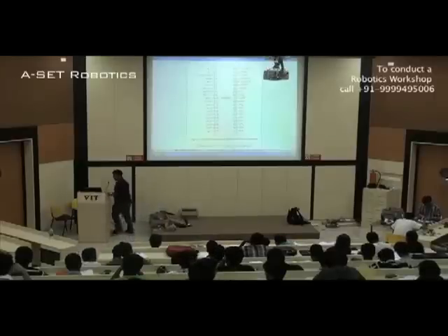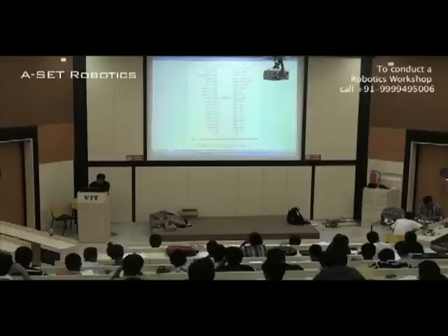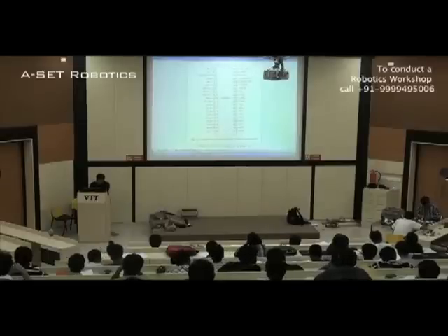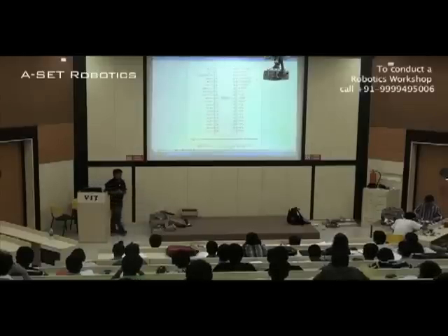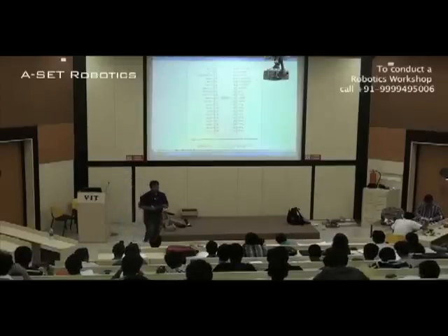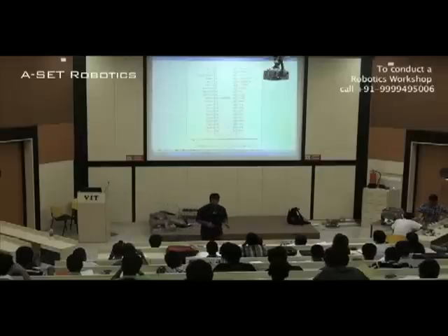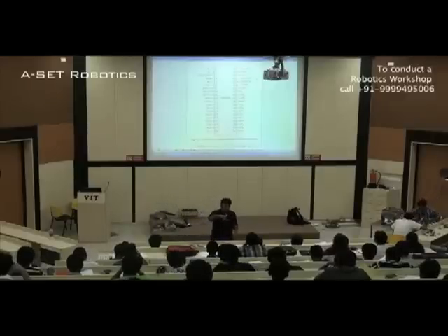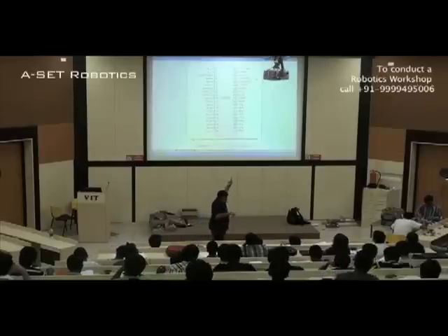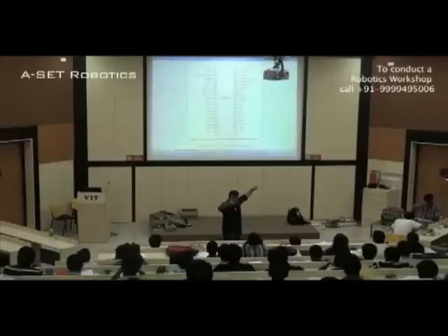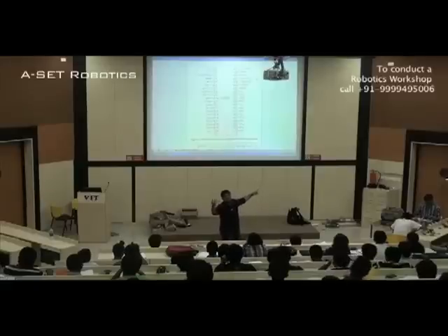Moving forward, reset n. Now there is a very important thing out here: over reset n there is a bar. Can you see that? There's a bar over it. Now this bar indicates that generally, whenever the signal is high, it is active. But out here, it is inverse, it is negated. So whenever the signal goes low, it becomes active.